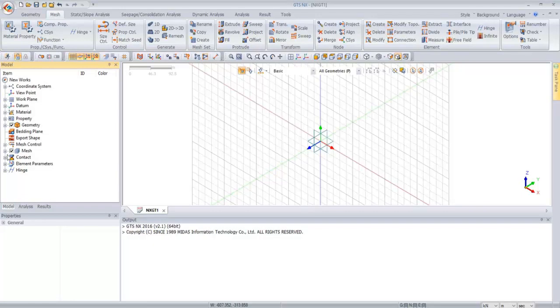It can only manage displacements. They apply a load, and it's just like a rigid object, and so it'll move around, but it won't reflect structural results as we will be able to, like forces or moments acting on the pile itself. So right off the bat, there's one of the differences from us and the Plaxis tutorial.